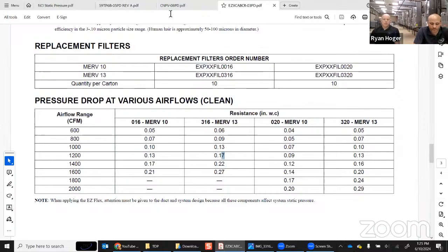With static pressure, the main thing we hear about is why you're questioned, or people are questioned, when they call with limit issues, specifically furnace related. We'll ask what the static pressure is because everything is perfect, but there's a reason your limit's going off. So you have to pay attention, and static is a good indicator. It's easy to check. It's a good indicator of what's going on in the system.